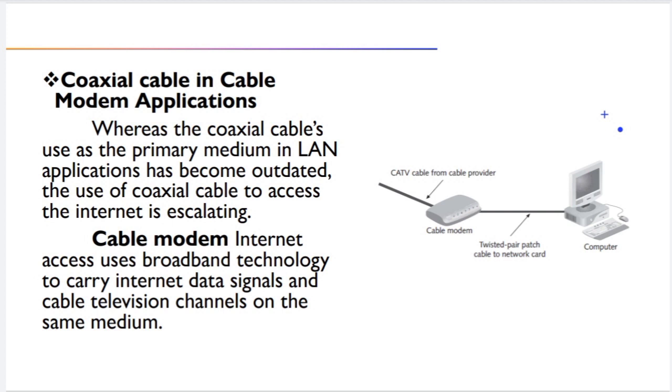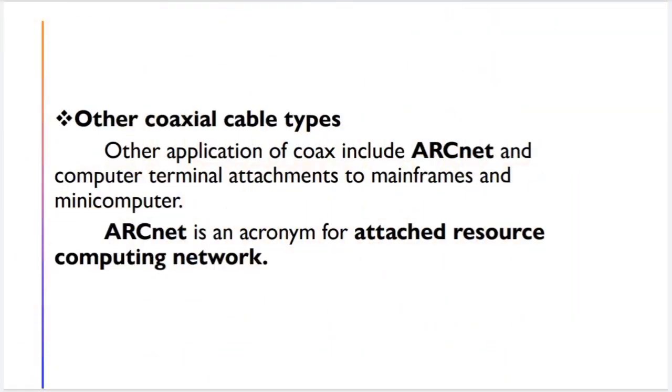Whereas coaxial cable used as a primary medium in LAN applications has become outdated, the use of coaxial cable to access the internet is escalating. Cable modem internet access uses broadband technology to carry internet data signals and cable television channels on the same medium. Other applications of coax include ArcNet and computer terminal attachments to mainframes and minicomputers. ArcNet is an acronym for Attached Resource Computing Network.